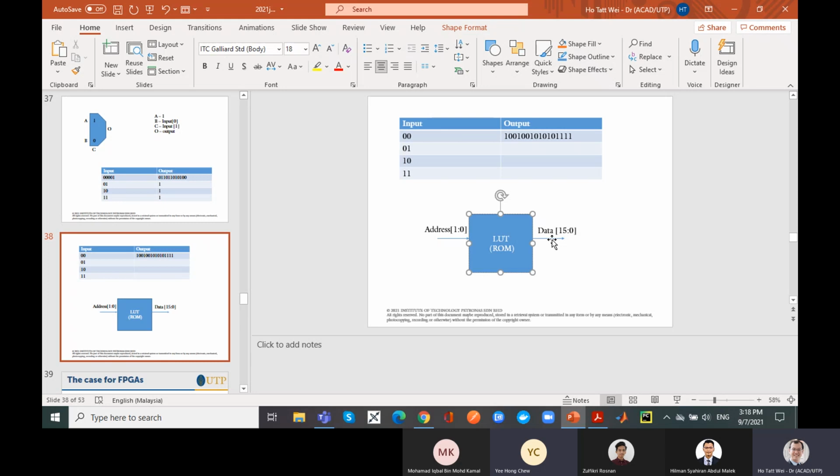You mean the propagation delay might be the same? Okay. Yeah, that's actually kind of the ideal lah, because roughly the access time in memory is roughly about the same lah, unless you're going into dynamic RAM. But for static RAM, usually the propagation time is the same lah, because whatever address you put in is kind of a random access, right? So propagation time will be the same lah. That's kind of the answer that I'm looking for lah.